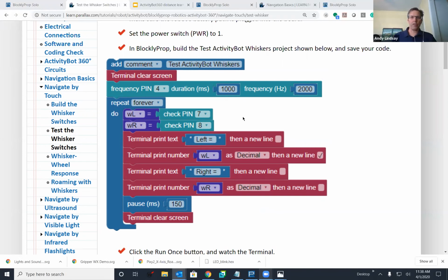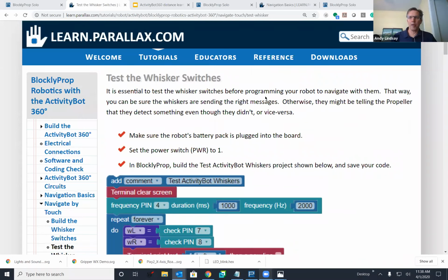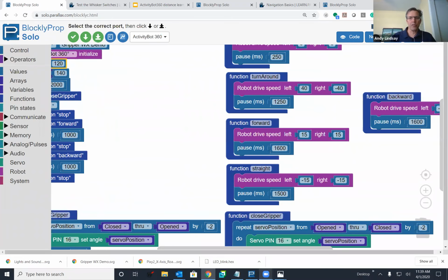Not overly gradual. For example, if you're watching it speed up and it seems to speed up over 2 or 3 seconds, that's unusual, or it would be something in your program that slowed down its tendency to speed up. It does by default gradually speed up over a short period of time. I think it takes maybe half a second to a second to get from 0 to full speed. Okay. And then there are blocks you can use to adjust that tendency to have it tell the servos to go to full speed immediately without taking any steps from 0 to full speed.